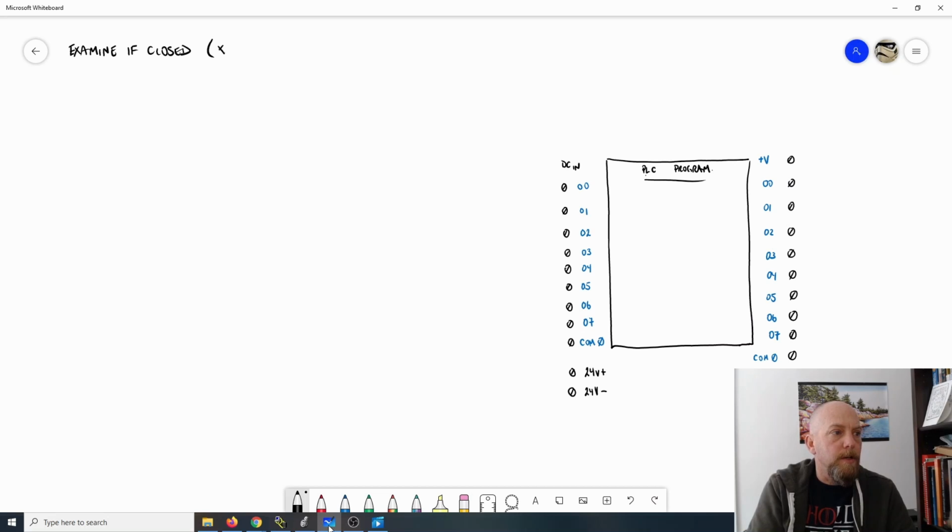Okay, that one is termed an XIC, and the symbol for that within our PLC programming in the Allen Bradley environment looks like this. It's backwards from the way that you would learn your ladder diagram symbol. So it's an examine if closed, but it's actually drawn as a normally open contact. The other one that we're looking at is an examine if open.